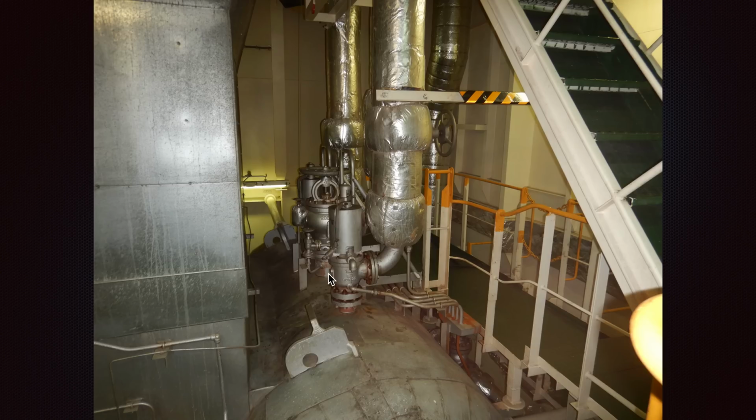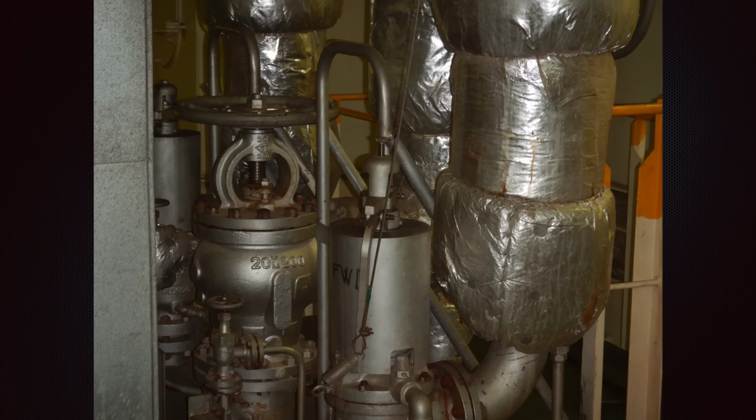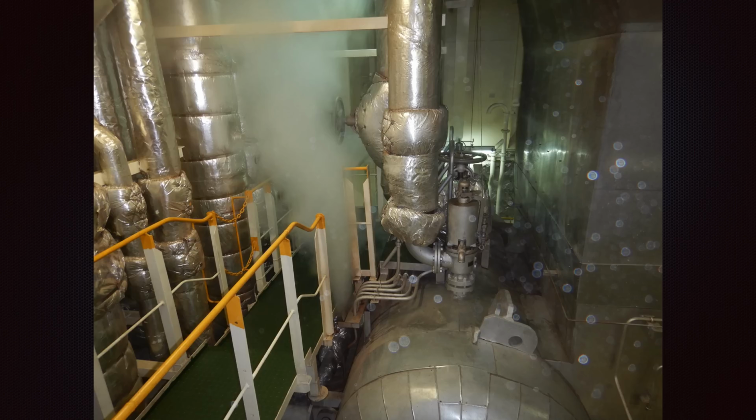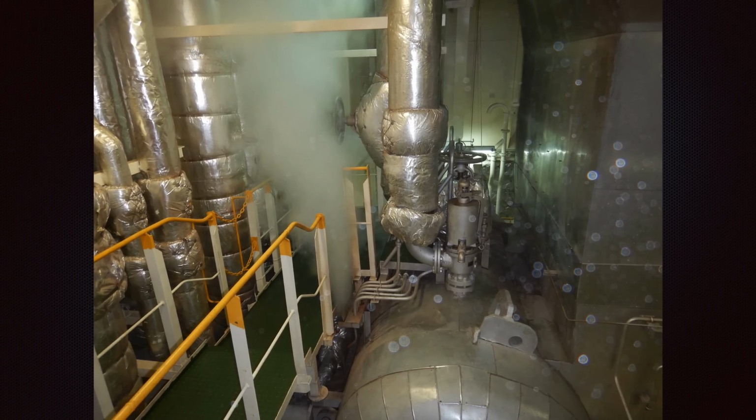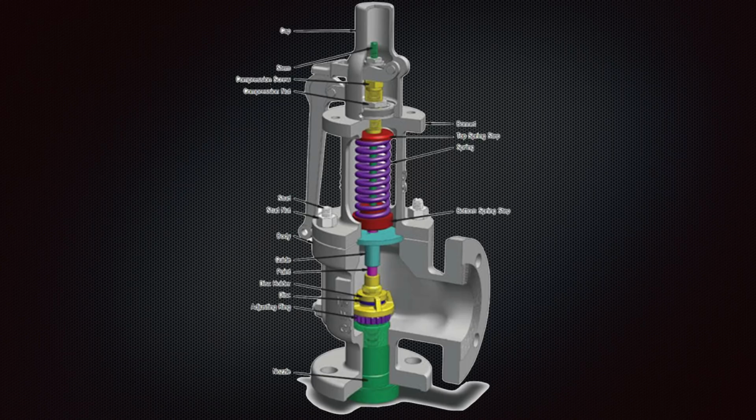Yes, we have some connection here that also drives it somewhere far away to the safe line, but I will show you how that operates, and you can see that some part of the steam also goes to the engine room. It's not so nice because it can trigger some fire alarms, and it's not a good solution. So as much as possible, make the design so the steam will be led to the safe area.